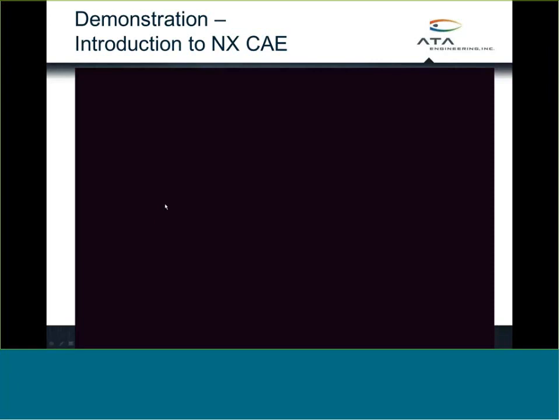The other thing that I'm going to be sure of when I look at this dialog box is that I have the Create Idealized Part checkbox checked. Now, it is possible, actually, to go straight from the part file to the FEM file by unchecking this checkbox. But as I described in one of the earlier slides, it's very useful to have this idealized part to create a higher level of abstraction that separates the geometry idealization process from the underlying part file itself.